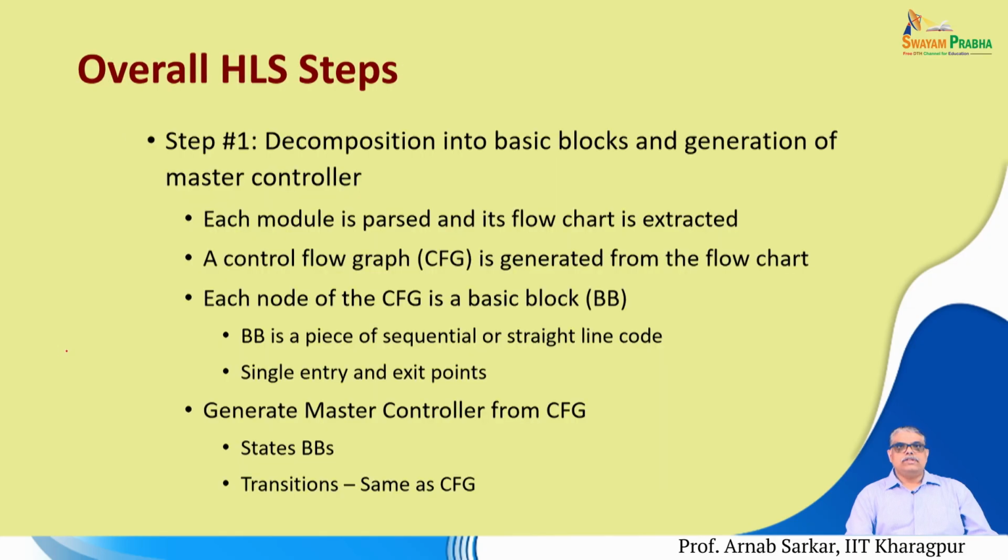So, in the last lecture we were seeing the overall steps in high level synthesis or architectural synthesis, which takes the design from the architectural level to the register transfer level design. We said that in high level synthesis we first decompose the model of the application that is to be designed in hardware into basic blocks, and we need to generate the master controller.